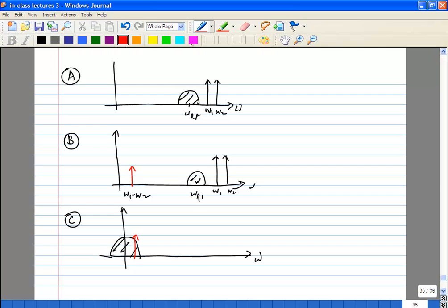All mixers will have limited rejection, so it depends on the even order distortion. You can represent the even order distortion of the system using something called IIP2. We looked at IIP3, which is the third order distortion. Similarly, second order distortion can be characterized through IIP2 of the system.